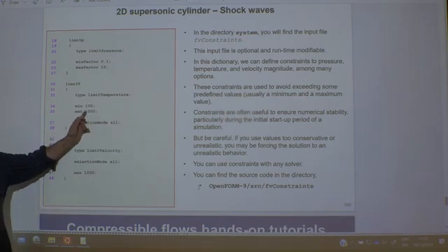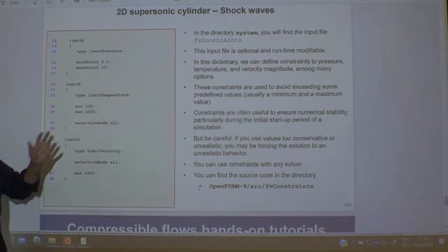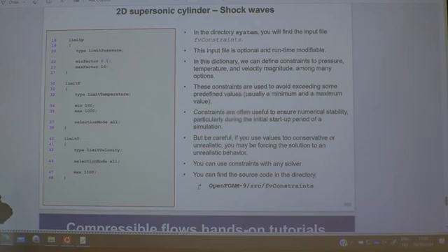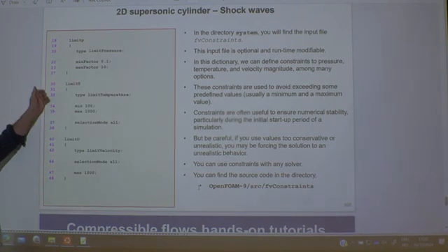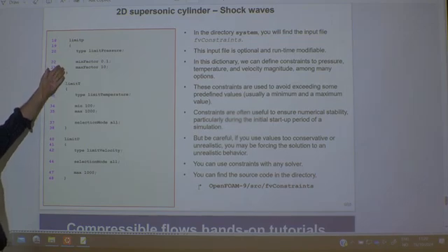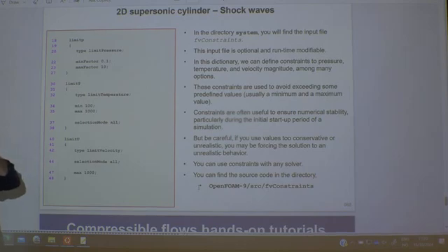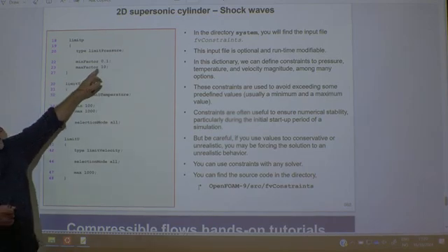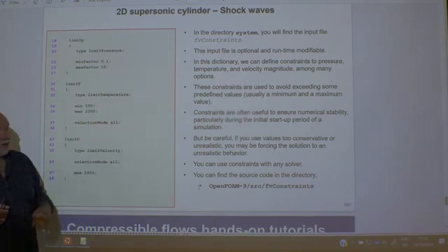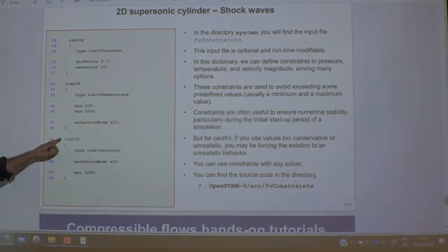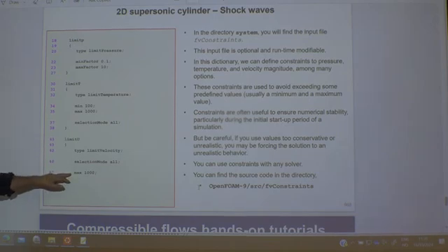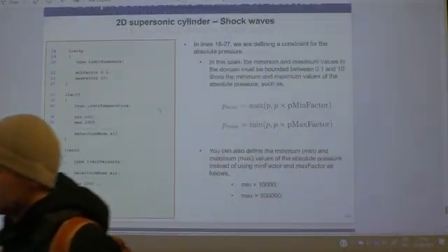So yeah, it should be possible to limit it, to say I want a temperature in this range, just to stabilize the simulation. Also the pressure can be stabilized, so that it shouldn't go lower than 10% or higher than 1000% of what you have. Also you can limit your velocity, setting a max velocity. I don't think you can set a minimum velocity. It should be 0 anyway. So these simulations can be rather edgy.